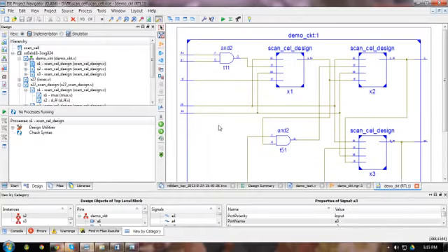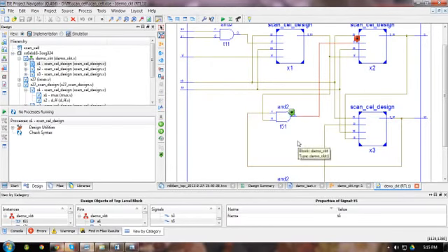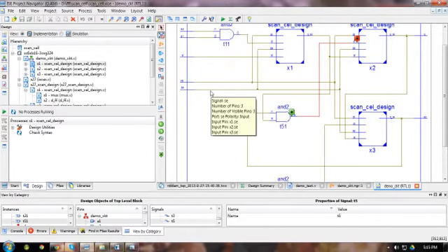What happens when you make scan enable equal to 0? It will operate in the normal mode, and this AND gate will also operate with the test inputs which you had given. You had given 1 1. Now that 1 1 has given the output 1. If this is faulty, it will give some other output, if it is fault free. Now I just want to see whether for the given 1 and 1 at this input, it has given 1.